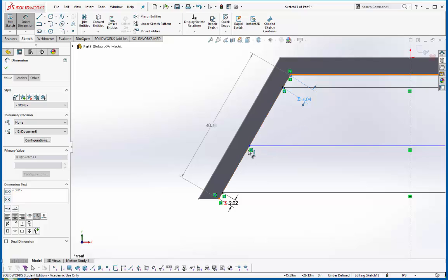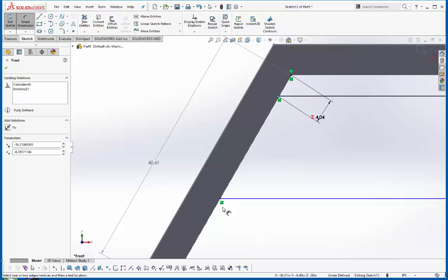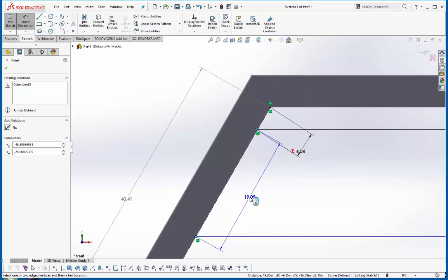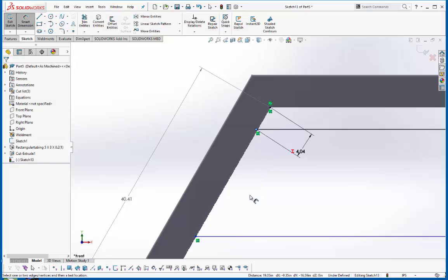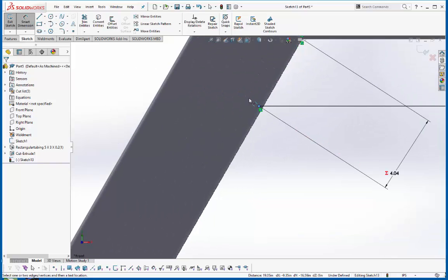Now what I want to do is to make the dimension between here and here, and the dimension between here and here equal. So I'll make a dimension that goes from that point to this point. And in the process of doing that, I discover I have an error in here, and I'm going to go find that error, and I'm almost going to guess that it's the tangent edge rearing its ugly head again.